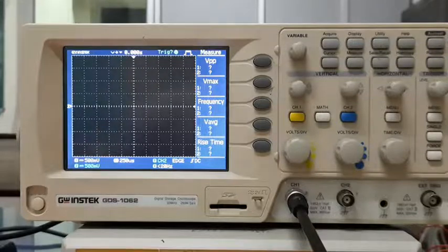So we can represent a signal, or the state of the signal, how the signal changes its amplitude in a given 2.5 millisecond time period, right? Or time slot or time block. Okay. Now, where is it important? What value should be set for our purpose? That is determined by the time period of your signal, because normally you want the display to show at least a couple of full cycles of the signal, to know its characteristics as a whole.